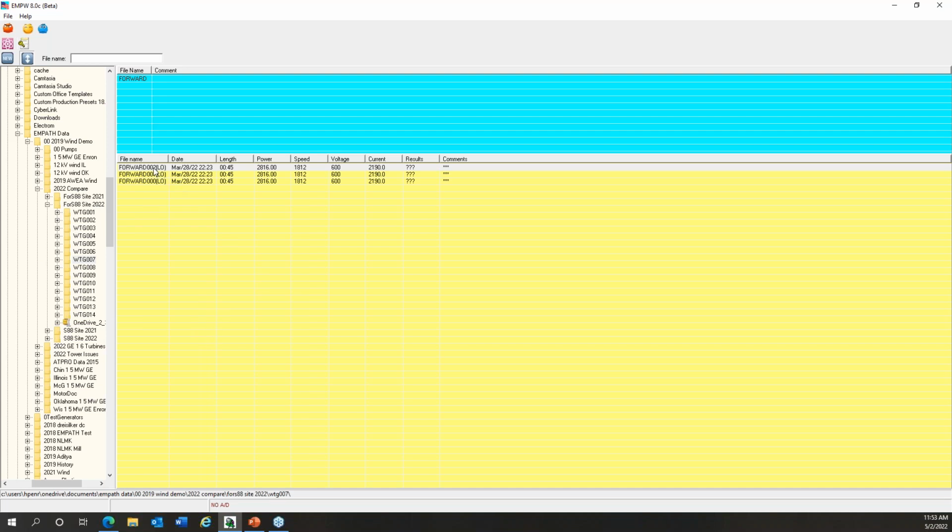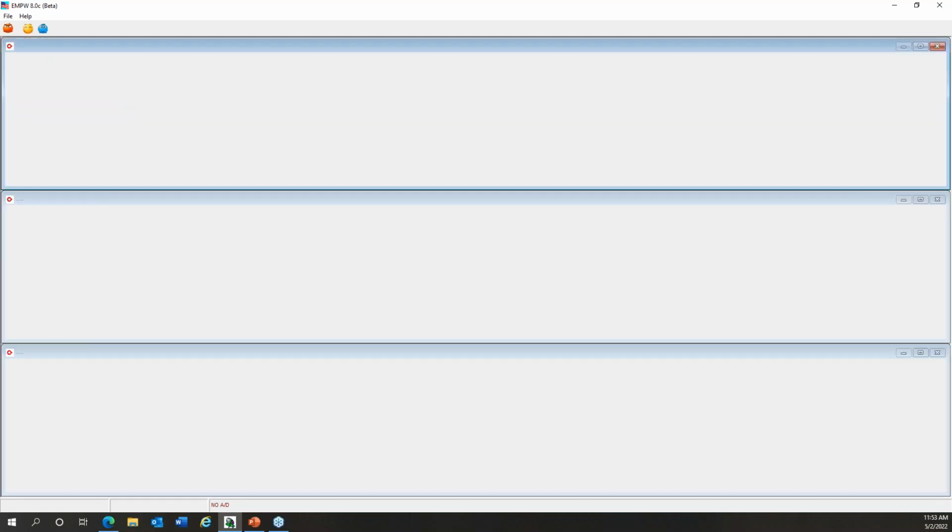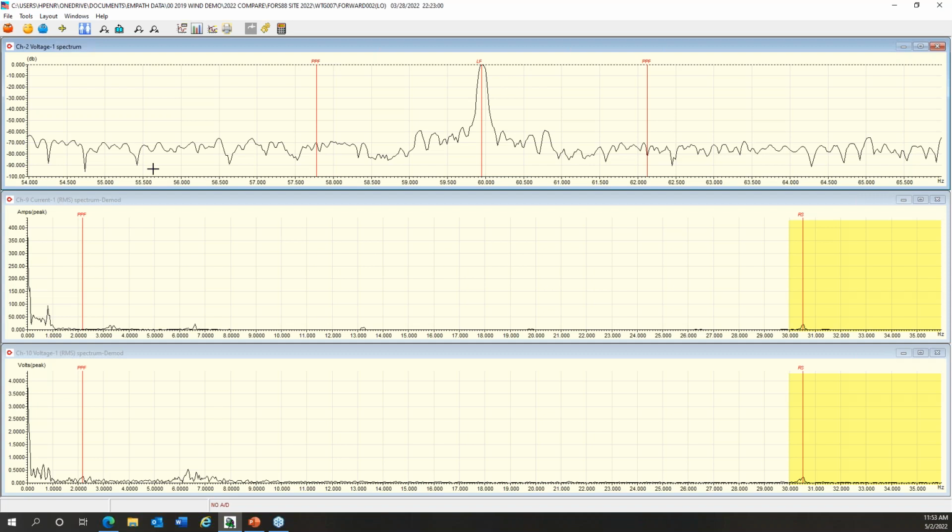So we'll look at an S88 first, because S88s have got their own idiosyncrasies. Not sure exactly which one I picked up, but this one actually has the running speed being correct. So they caught this at just the right time. This is a 4-pole machine, in this case running at 1831 RPM. Pole pass frequency looks wrong. No, there it is. Sometimes if I don't see something, I'm going to try to look right around 1 hertz, but that's not the case here.